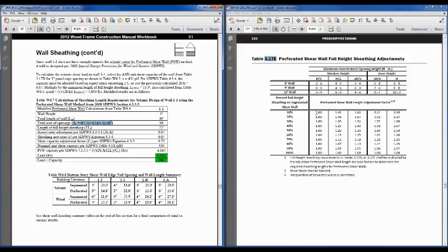What this table in the wood frame construction manual does over here in 317E is it assumes a maximum unrestrained opening height. So it's going to assume that if you've got a 6-foot opening, that's going to be present at all of your openings. This equation in this wind and seismic standard actually allows you to calculate your exact full height, your exact openings, and so that allows you to sharpen your pencil, and you see that that wall now works, even though it's pretty tight nail spacing.